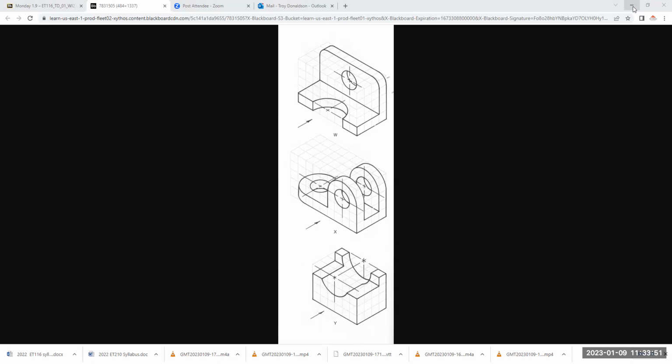In model space, the object zooms because now I'm in model space, right? So we don't want to use the roller mouse to size this. We want to pick an exact scale. That's here, right here. But you've got to be in model space within paper space. Hard to say, but you've got to be in model space here, not paper.